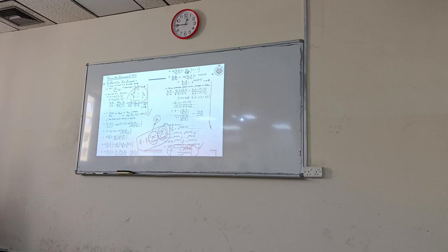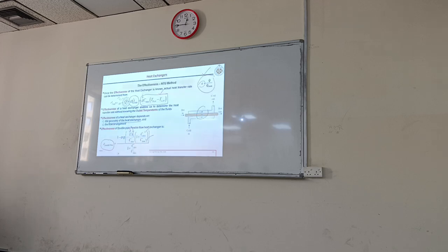All these equations. Okay, so here these two are given. Here is for parallel flow. Here now we can introduce this number NTU and this one as small c, the heat capacity ratio, for effectiveness. Look, in this equation normally we know U, and we are saying this method is applicable when area is given. So area, U, and the MCP product are also given. So just put them there and find out effectiveness, and from the effectiveness find out heat transfer.